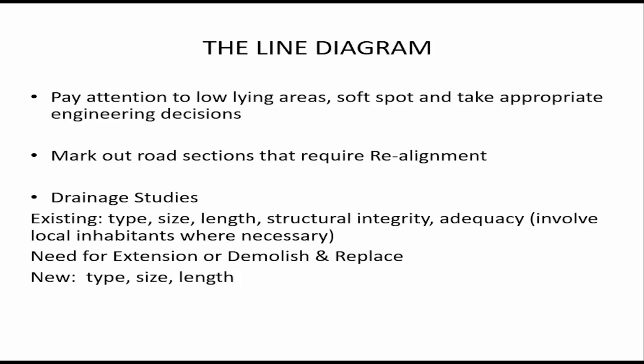So you need to check and assess the existing type of the drainage structure: the type, the size, the length, the structural integrity. That is where the hammer comes in. You knock, you hear the hollow sound, then that gives an indication that it's weak. And then its adequacy.